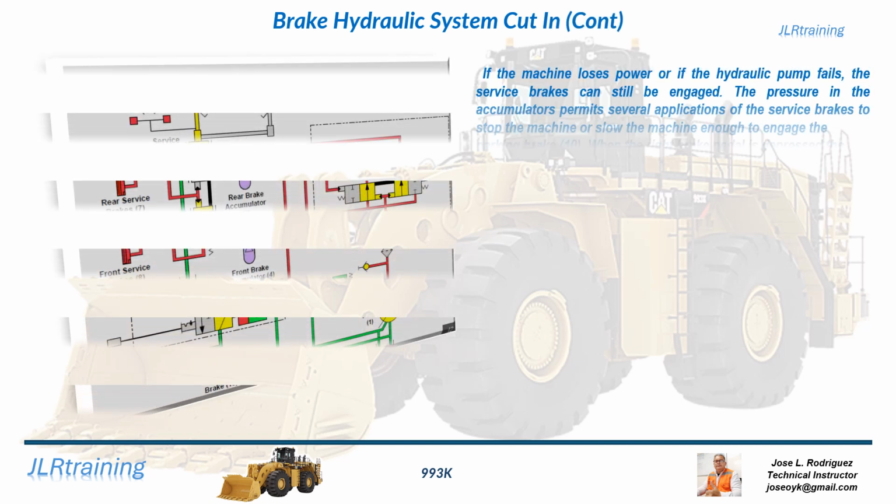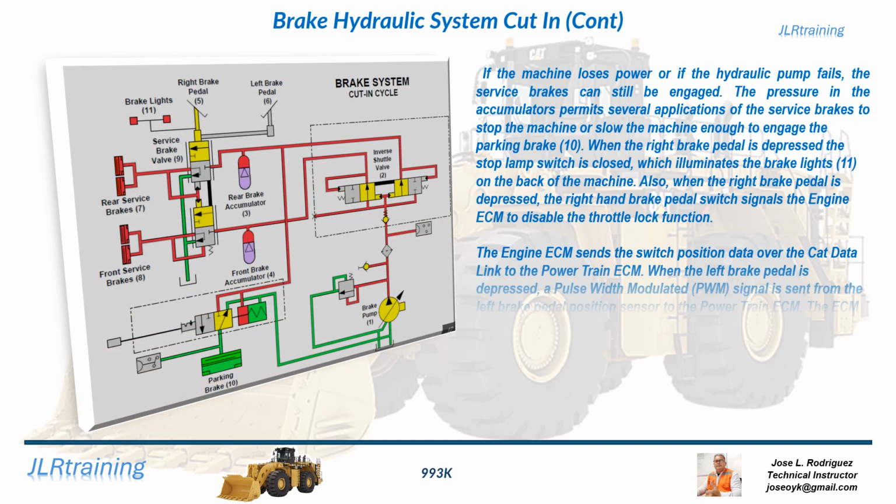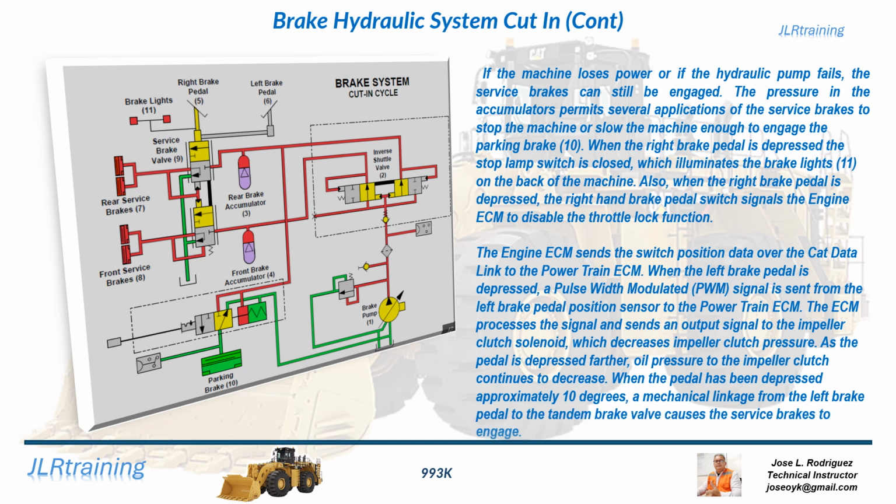Brake hydraulic system cut in, continued. If the machine loses power or if the hydraulic pump fails, the service brakes can still be engaged. The pressure in the accumulators permits several applications of the service brakes to stop the machine or slow the machine enough to engage the parking brake.